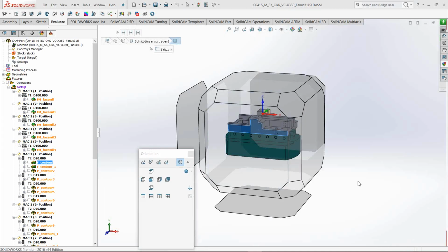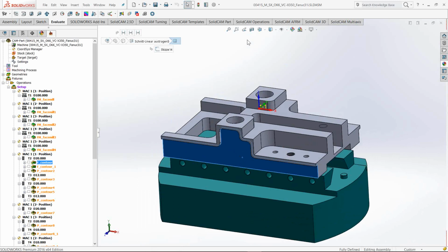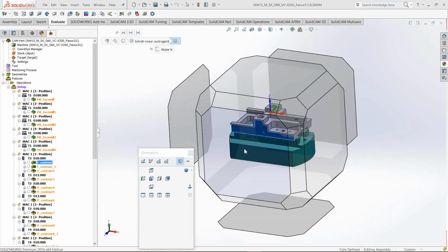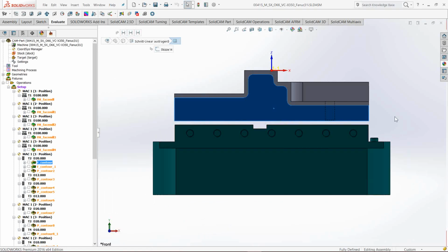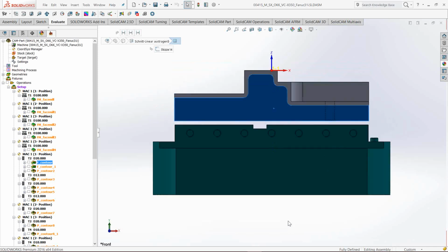First of all, if I'm in front of the machine and I want to mill this surface, here is my tool, and it's vertical. In order to machine it, we need to rotate around the X, and here is the X vector. Here I have the 5-axis machine, one axis around X and another around Z. To machine it, you need to rotate around the X by positive 90 degrees. This is the first angle pair, or let's say one of the angle pairs.